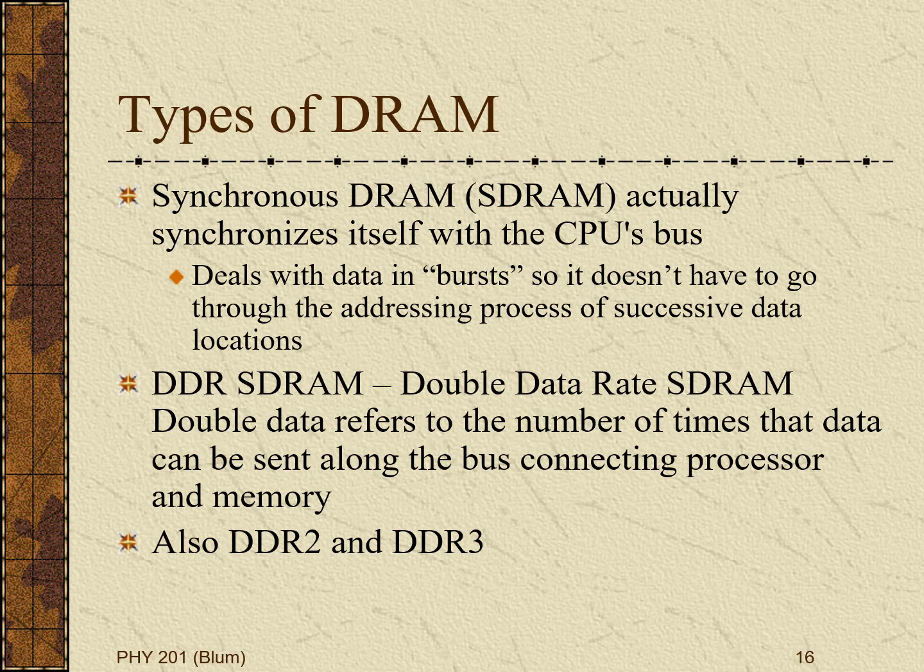A binary clock is 0 and 1, so 0 to 1, 1 to 0, back and forth. The change from 0 to 1 is known as an edge, and 1 to 0 is another edge. And DDR, double data rate, means that you did something on both edges.